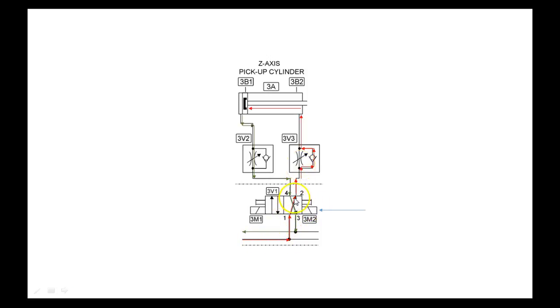So right now, the pressure is going up, right? You understand? It's coming up here, and it's doing what? Pushing it this way. My exhaust is coming. It's going to seat the check valve. It has to go through the flow control valve and back out to the exhaust. Okay, so it's going to push in this direction.